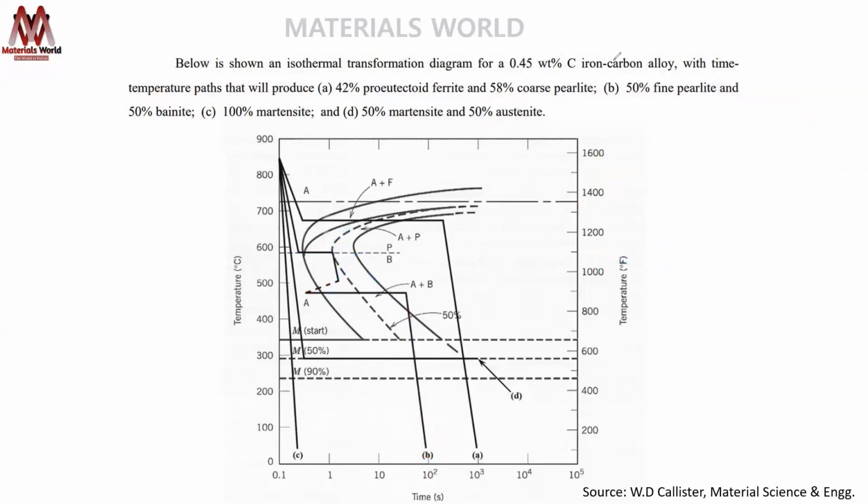Similarly, in the previous one, if you go like this, as in the question given, 50% austenite is converted to pearlite, and it's not crossing the transformation starting line, so it will not start the transformation. It is crossing this martensite transformation line, so the remaining will be transformed. Okay, it's a very simple logic. Once it has crossed the finishing line, there is nothing remaining.